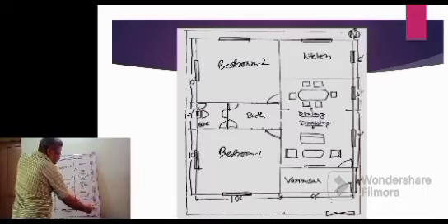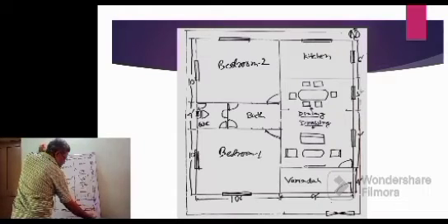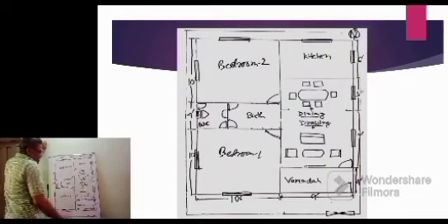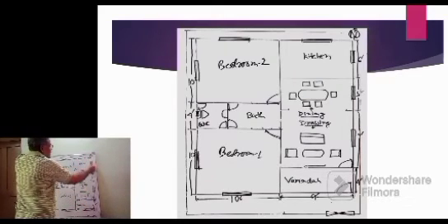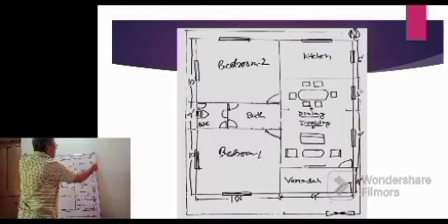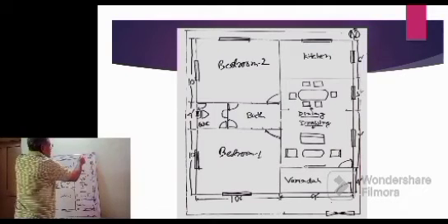We have kept one veranda that is 4 feet width and 9 feet long. People are entering from here. So this is the gate of your plot. Then this is the drawing room. Then comes the kitchen. Kitchen minimum width should be 6 feet. We have to keep 6 feet minimum, and this side is 9 feet. I have already discussed, this is 9 feet.